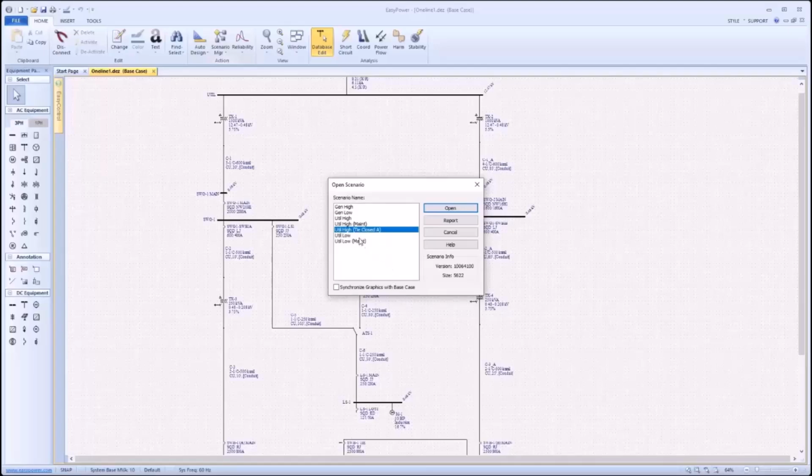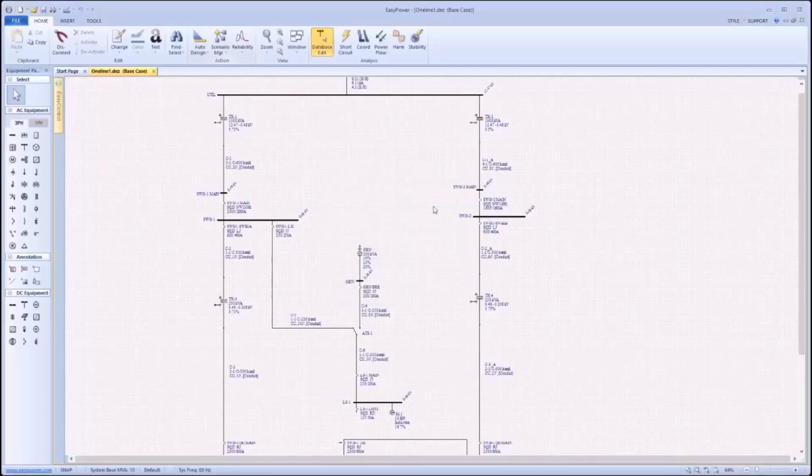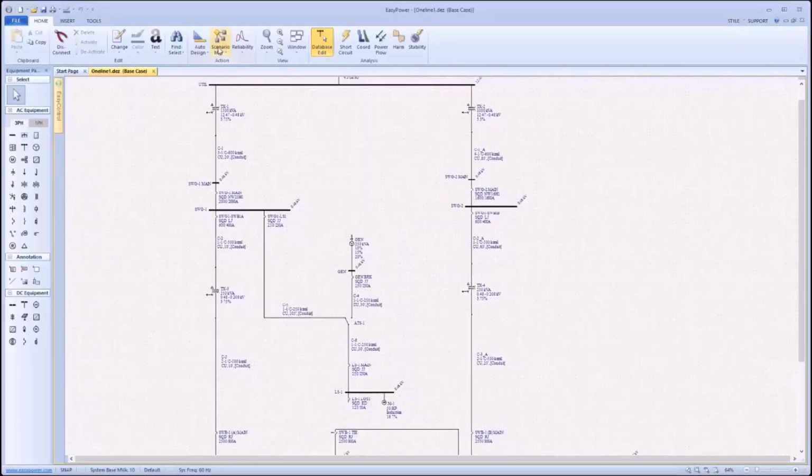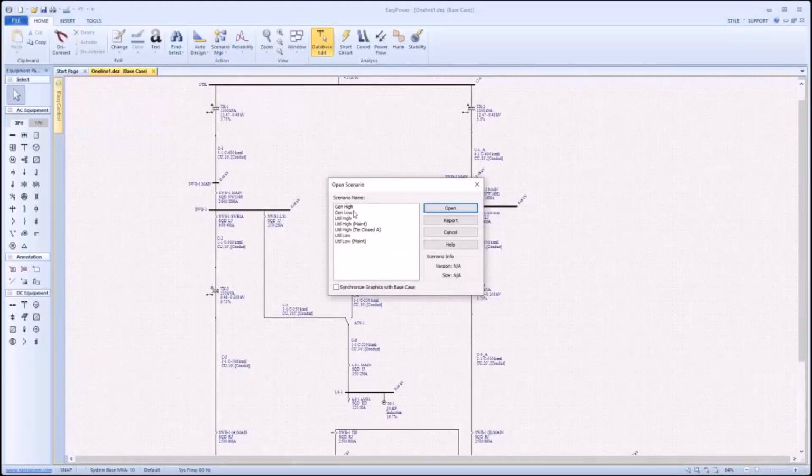And we have a utility high and a utility low with maintenance settings applied to both switchgear 1 and switchgear 2 main. So pretty good. We could easily run, and we will here in just a minute, cases for just the maintenance together. I'll show you how to do that in some configurations here, and we could run our 5 or so cases that we have for just normal settings with utility high, generator, tie close, etc.